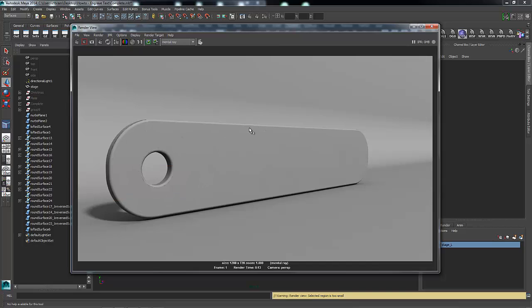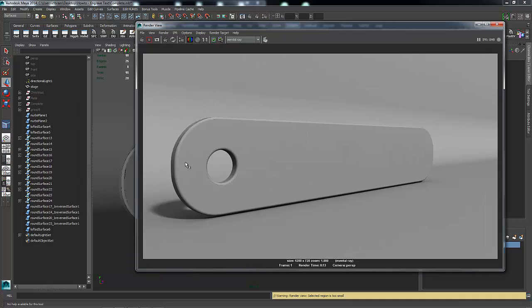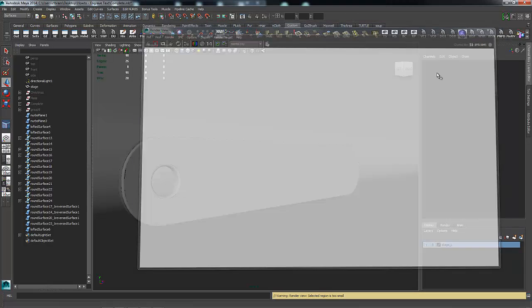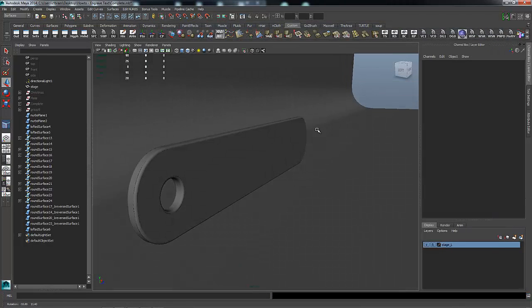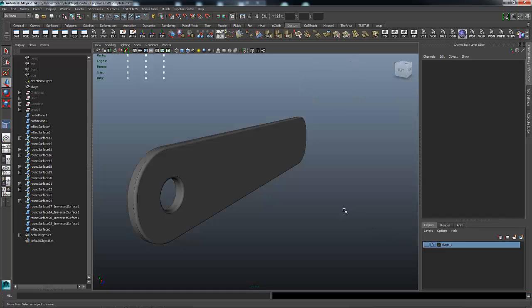They're not visible. Well, they're kind of visible, but there's another thing you can do when you render NURBS to make these completely invisible. But for our purposes, you'll never see them because this is going to be dark, and if you pass this to an STL application, it's not going to worry about the render tessellation so much. So anyway, now we've got this cartouche shape, so now we need to engrave the letters into it.